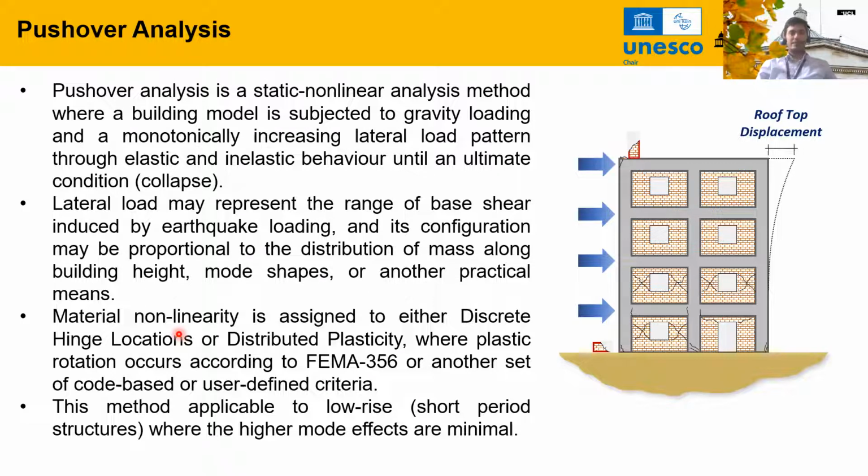So pushover analysis is a static nonlinear analysis method where the building is modeled into a numerical model, which is subjected first to the gravity loading, the dead and live load, and then we apply a lateral load pattern, which is monotonically increasing until we get a failure ultimate state, which we call collapse. The lateral load may represent a range of base shear induced by earthquake loading, and its pattern might be proportional to the distribution of mass along the height, the mode shape of the building, or other practical means. There are several methods of pushover analysis available in the literature.